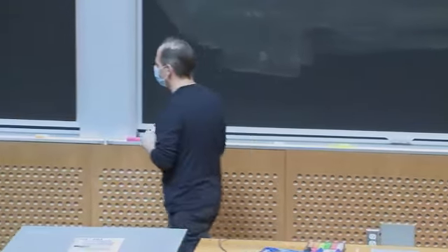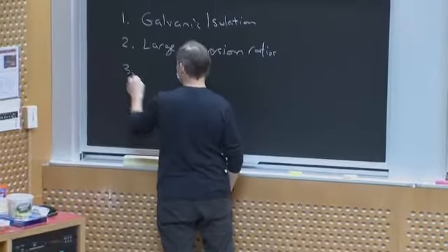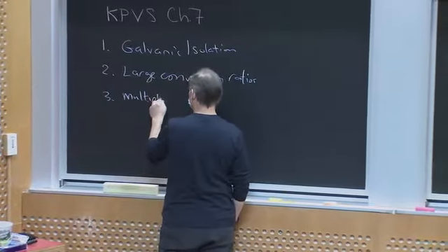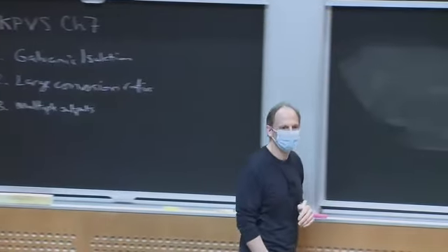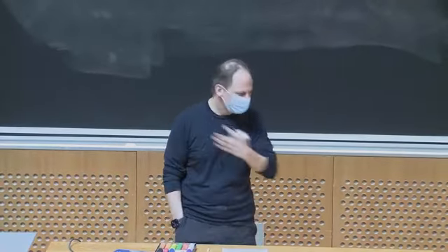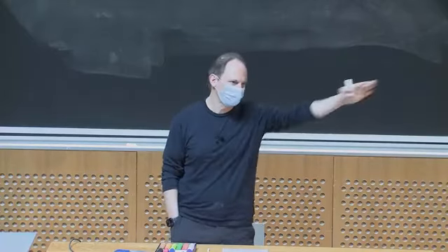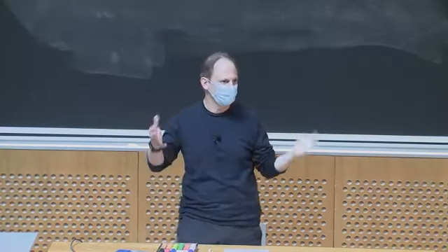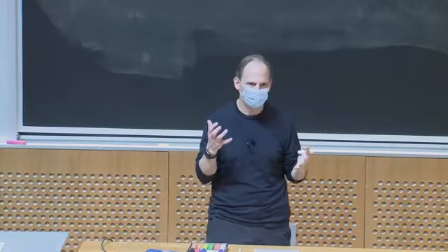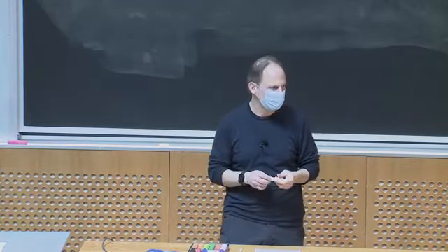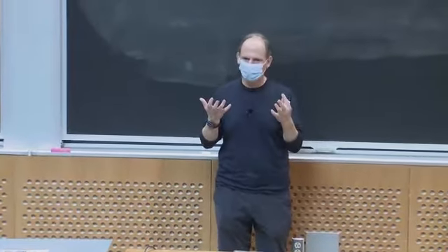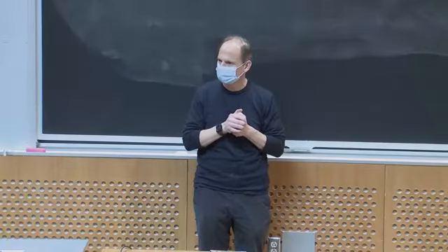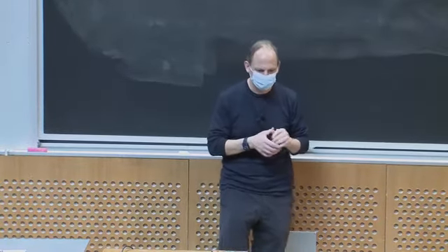Okay? The third reason that's very common is that we can do multiple outputs. So, a typical power supply for your computer or something, maybe you want plus 12, plus 5, minus 5, so you can supply a whole bunch of different stuff at once. And yeah, you could build separate power converters to do that, but wouldn't it be nice to build one converter that does it all in a more compact form factor? And having transformers at our disposal lets us do that. And lastly, which I don't put up here, it turns out transformers just open up the range of topologies and structures you can put into a converter, and thereby help you design some interesting things.